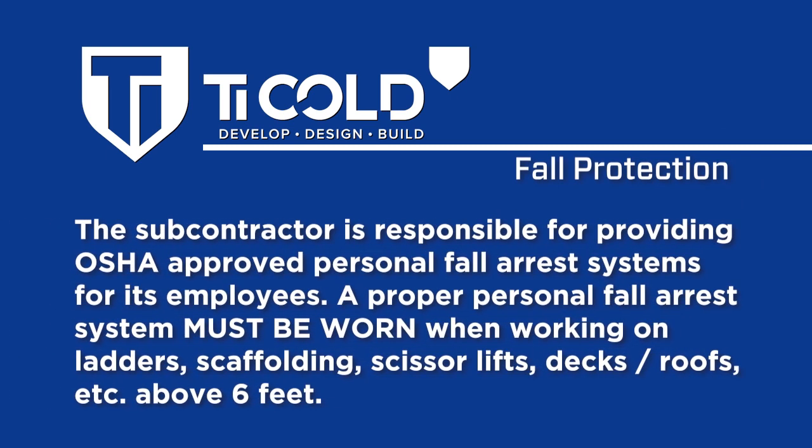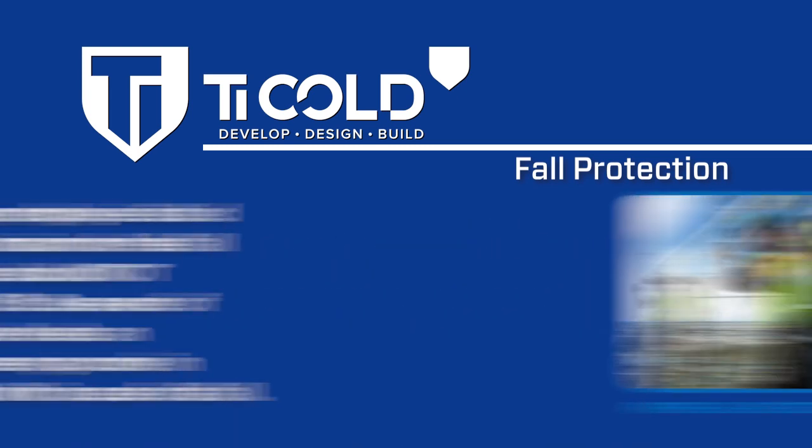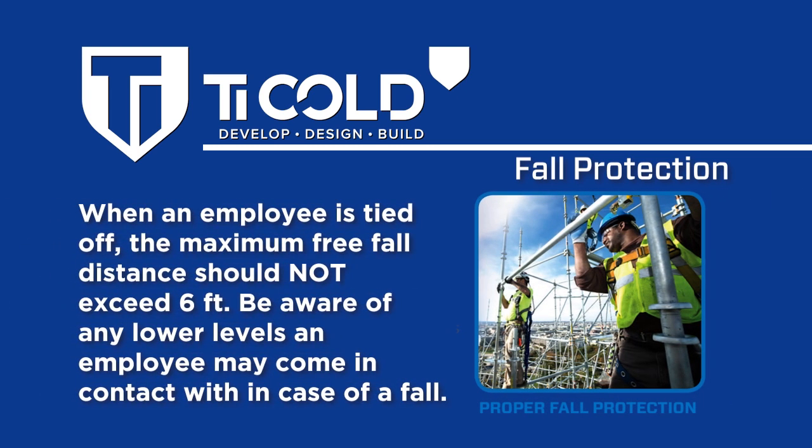Fall protection. The subcontractor is responsible for providing OSHA-approved personal fall arrest systems for its employees. A proper personal fall arrest system must be worn when working on ladders, scaffolding, scissor lifts, decks, roofs, anything above 6 feet. When an employee is tied off, the maximum freefall distance should not exceed 6 feet.